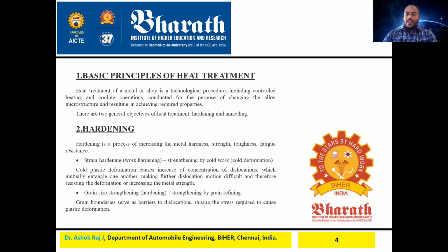Grain boundaries serve as a barrier to dislocation, raising the stress required for plastic deformation. If a grain is very small, when you apply any force or do heat treatment, the dislocation crossing is very difficult.